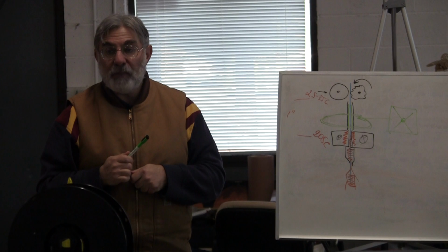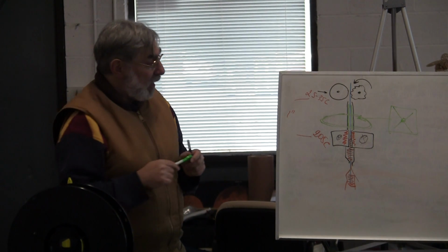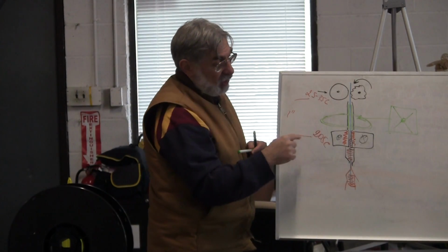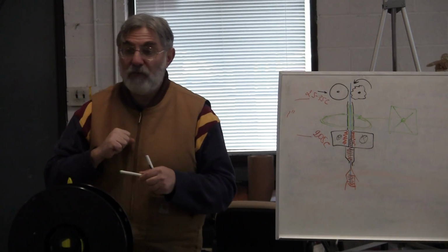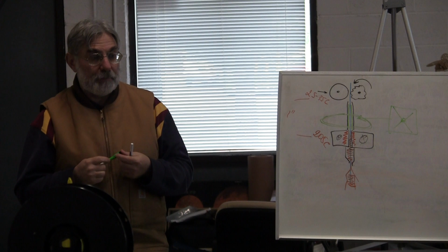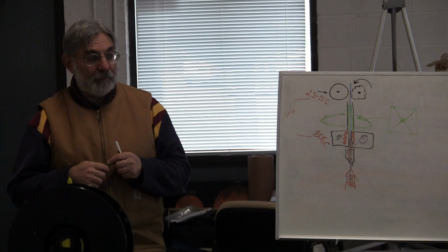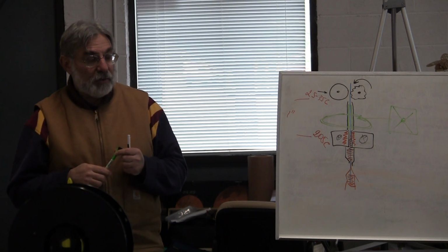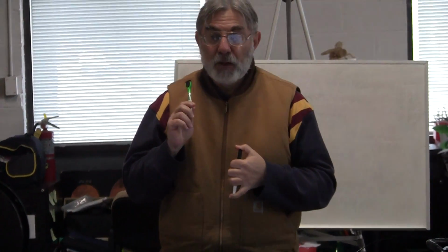Okay? And so people came up with what are called all metal extruders. All metal extruders don't have a Teflon tube in there, but they blow air much more aggressively. And they try to remove the heat much faster. The metal tube is going to be conducting heat. Yep. Teflon is not a good conductor of heat. Yep. Do we have that metal extruder? So your extruders in these machines are Teflon tube extruders. Okay. Do you have that one above?